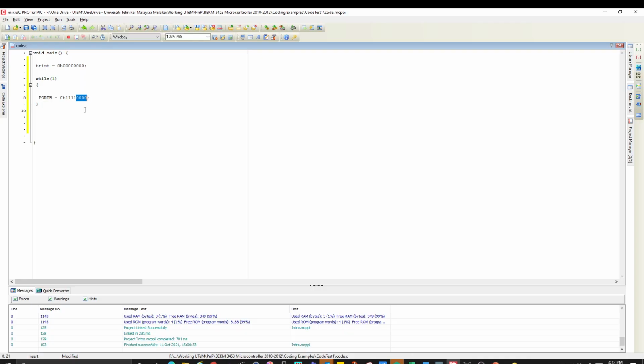Alright, so this is the one. So let's compile it. Do you have a problem or not? Let's look at this. You can see that now this is the whole program, right? You're setting up the port B as the output, and then you are giving the signals 5 volt out for the 4 pins and another 4 pins as 0 volt. So this is by using this register port, to make sure that you do not confuse it when I'm talking about the registers.